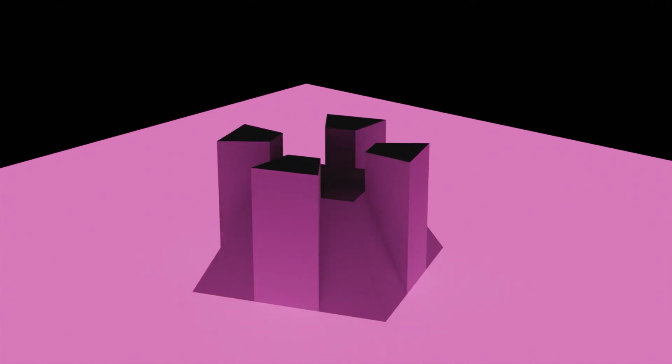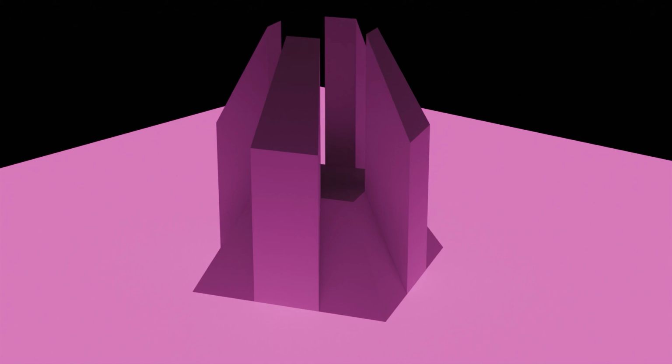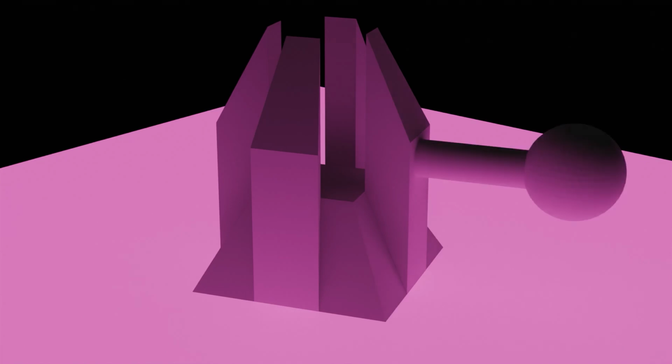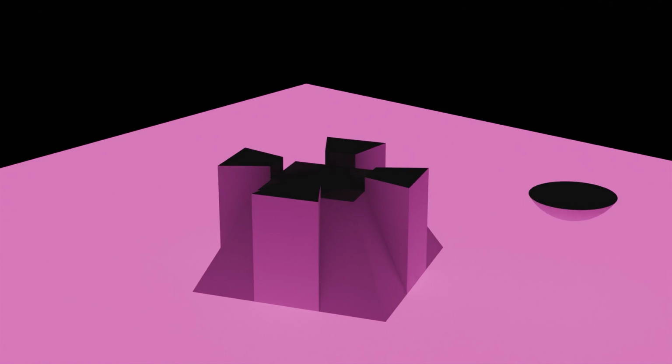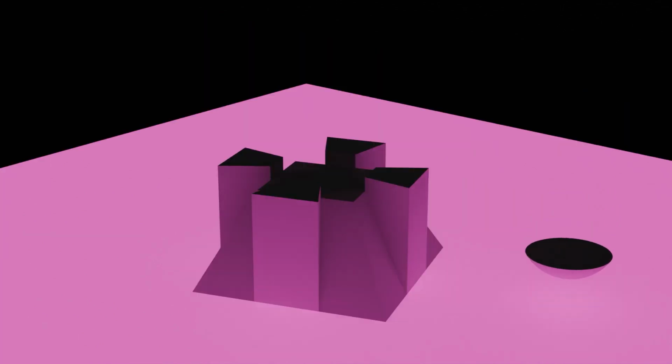Imagine that you have a shape you'd like to print. The way you print it is the printer starts at the bottom and it's going up and up and up until it's printed. Simple. But there is a pickle, because imagine that to this shape I had a cylinder with a ball at the end. Now if we try to print the shape, it will work just fine, until you reach this point, where you will have a flying shape in the sky, and that shape will fall on the ground.